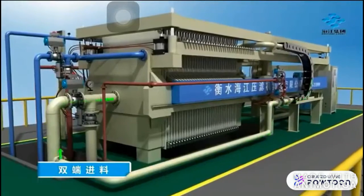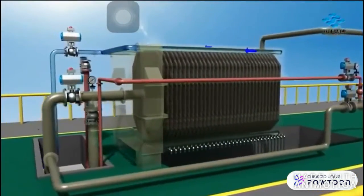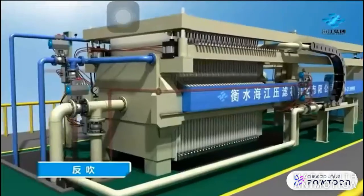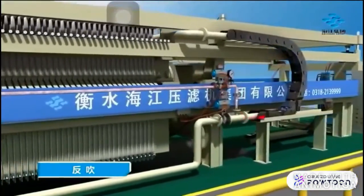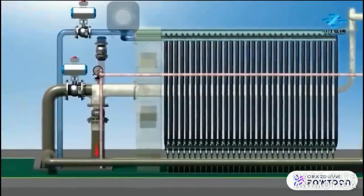The filter press is constituted by a system of stacked plates that inside have a filter of paper or cloth. The foundation of this equipment is to use mechanical or hydraulic pressure to force the passage of the syrup through the plates. This causes the solids suspended in the syrup to be retained in the filters, and a clarified syrup is obtained.